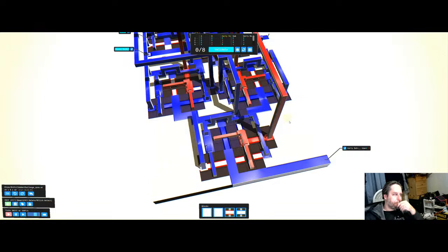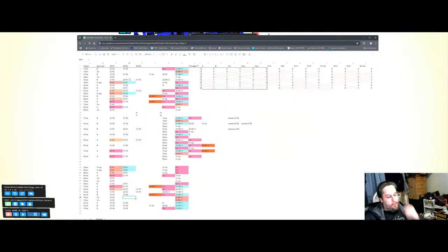But in any event, there's going to be reasons that you're going to deviate from your main backbone, and you're going to have splices for that. And so, definitely pretty common to have at least one or two cans every 8,000 feet or so, depending on the design. So, with that being said, you would have something like this that would show all the splices and where you go from one can to the next, how it goes.